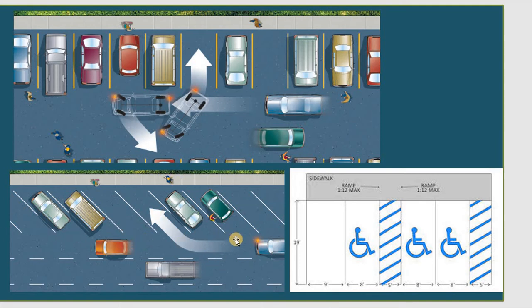So if you have no choice, you need to design this one, but if you have a choice, please use this one, which is the best design for parking, 90 degree. And we need a crossing for the people using handicap parking. They can go to the building, and a ramp so they can run the wheelchair. This is everything about the sign from the parking lot.